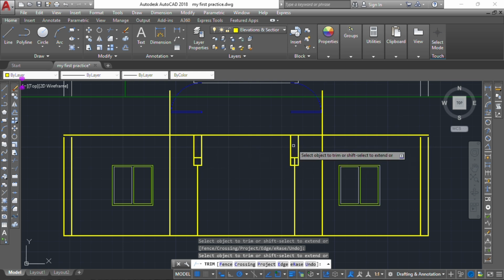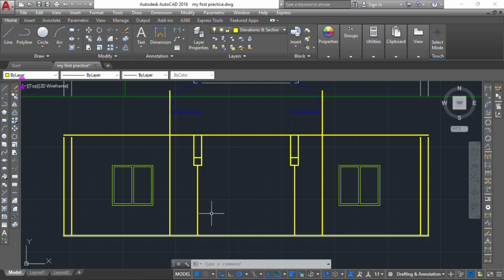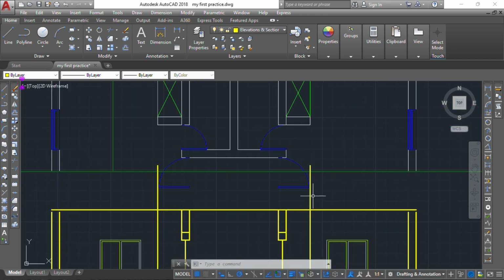This is a method of indicating your door, the door will cut across. And another way, you can just extend this line, these walls. You can extend it down to the ground floor, indicating that it is a wall, but a door is in between the wall. But this is just a meaningful way of doing it by indicating only the door. And here is the lintel on top, and here is the sectional area of the remaining courses of our blockwork, right?